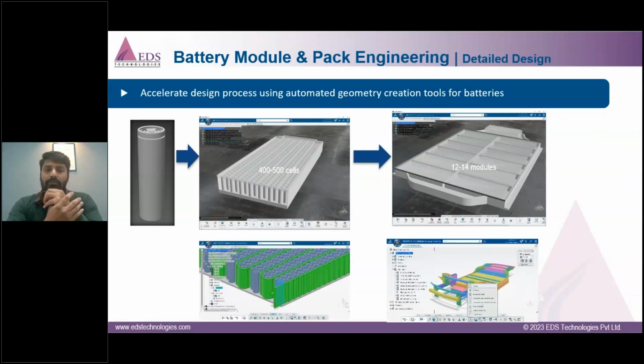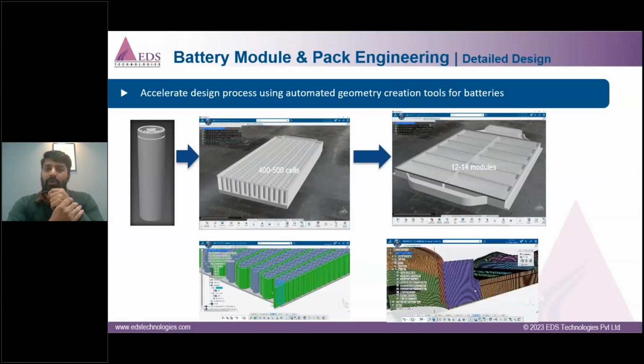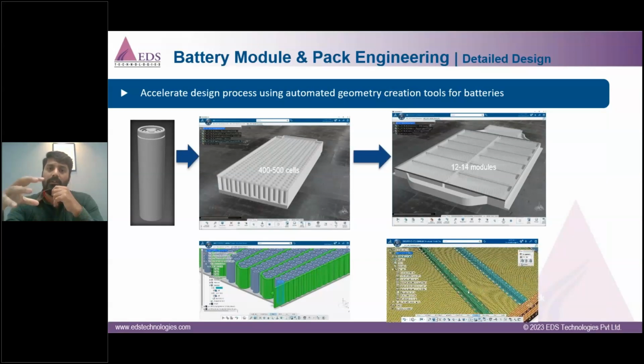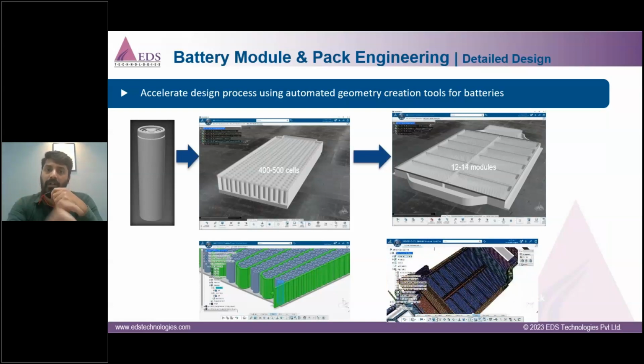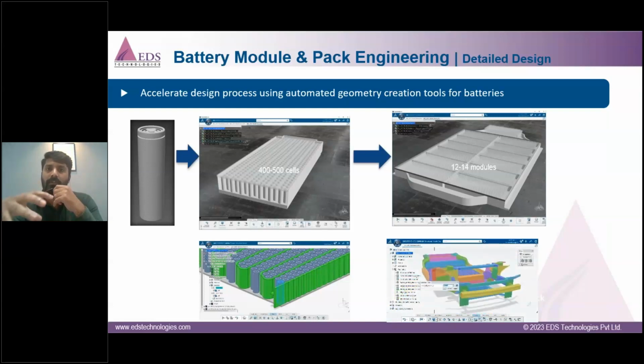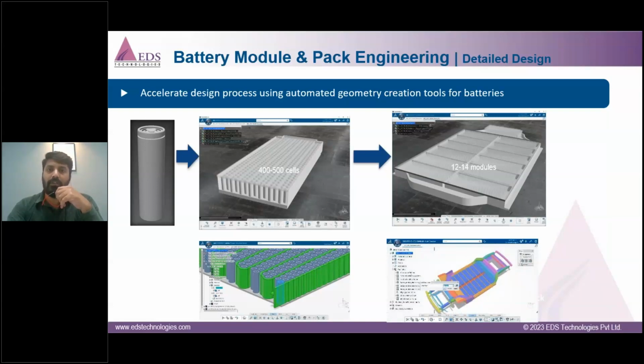When it comes to the detailed level of modeling, the 3D Experience SIMULIA always provides you automatic tools where you can reuse the existing FEMs, part-level FEMs, in your assembly. Thereby you need not spend much time creating your complex assembly-level FEM model. At any point of time you can reuse your existing FEMs, and thereby customize them for your geometry analysis.